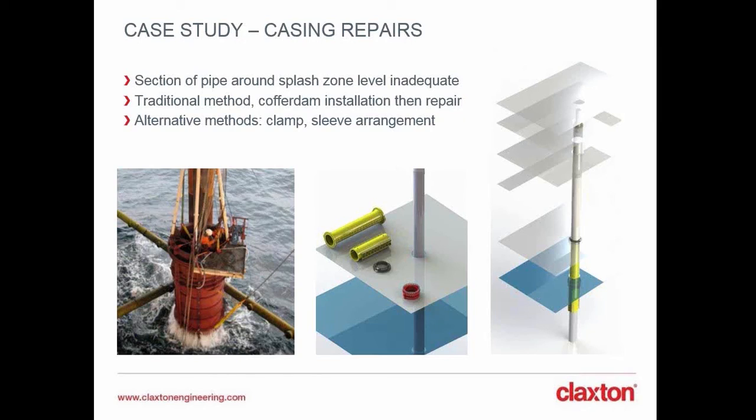An example of an alternative method currently being designed for a project in the Middle East makes use of a subsea clamp, a load shoulder, a transition sleeve, and top weldable segments, that's flanges and plates. These are shown in the middle sketch for installation, the 4 main components. What is not shown there is the weldable segments. That's prior to installation, and then the sketch on the right is after installation, including the weldable plate all the way to the top.